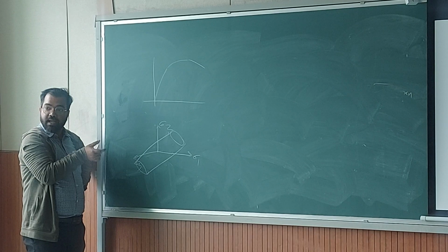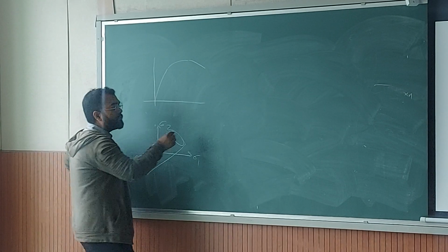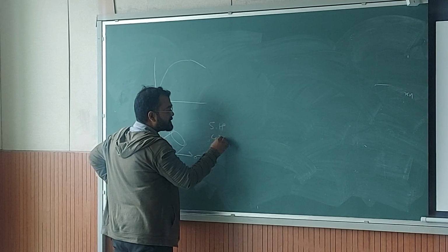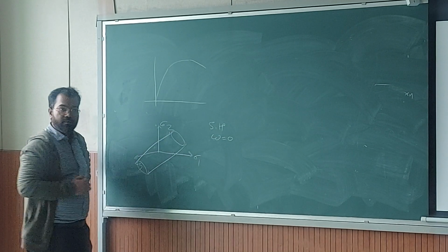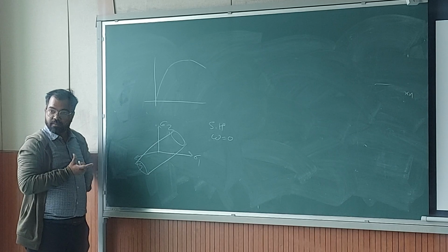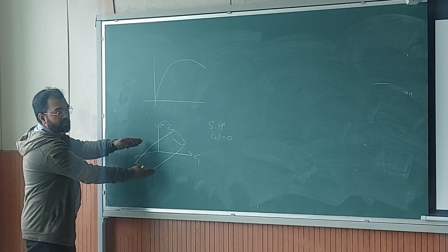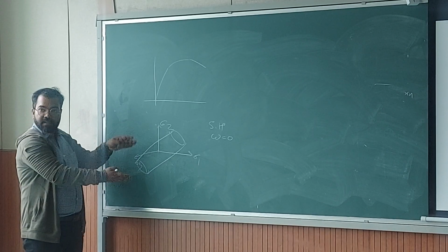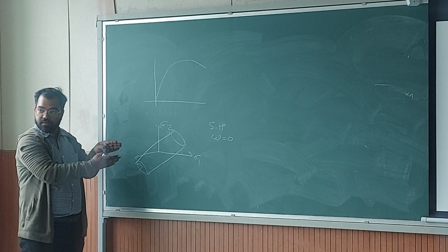So when strain hardening happens, so for the domain where you have strain hardening happening and omega is equal to 0, for a very long period of time omega will be 0. So in that case this radius will keep on increasing, and when omega starts developing, then it starts decreasing. So then softening happens.